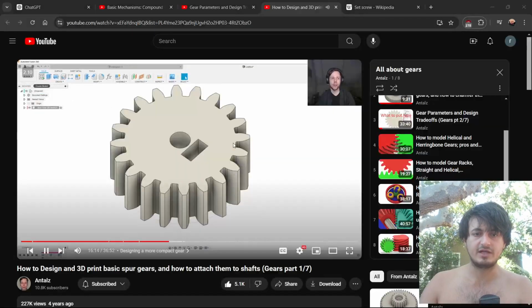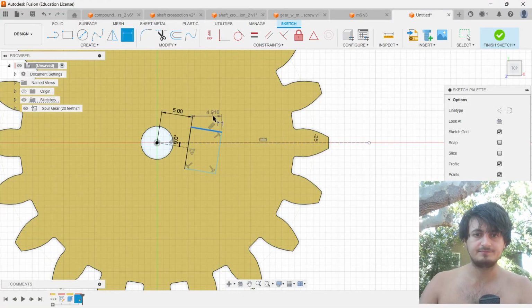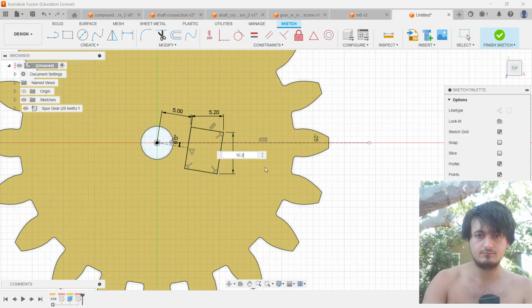From here, everything is basically the same as before. So create a new sketch on this inner surface here. I hit C for circle and I look for this midpoint constraint. I make it 6.2 millimeters. Finish the sketch, E for extrude. Again, 2 sides. And on the one side, I will go for all.